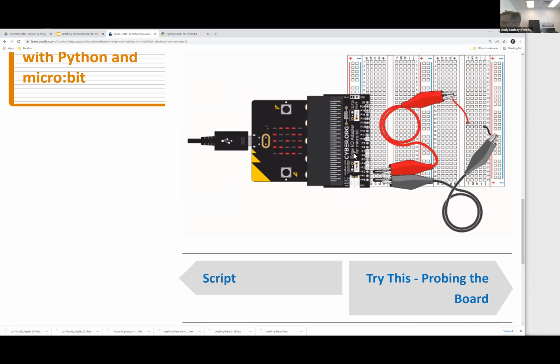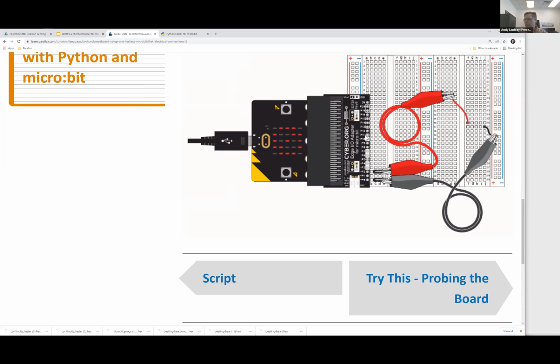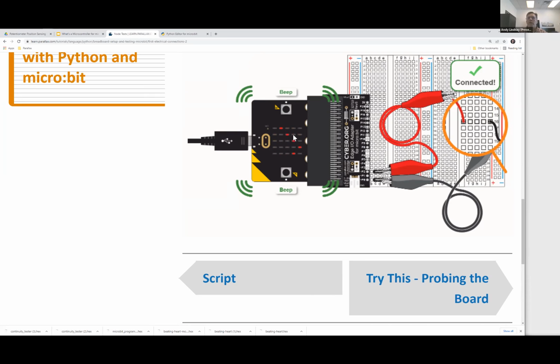I'm going to need to check with our supplier about that because that's not something that we ever want to have happen. So make sure that your wire sinks a good 1/4 inch into the socket. And once you've plugged both wires into 16, we want to verify that you can see a check mark on the Microbit's LED display.